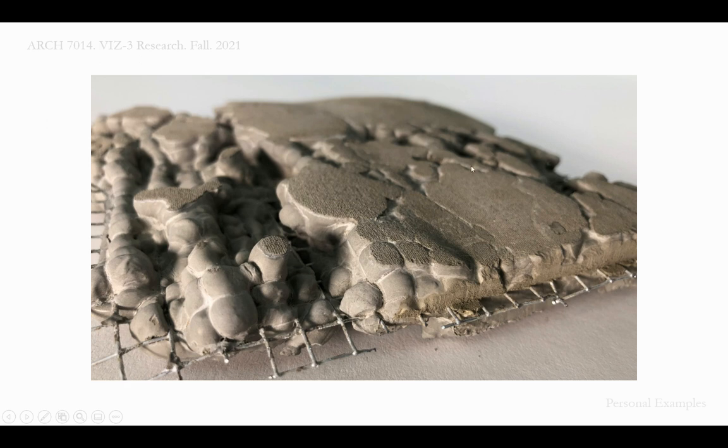Sometimes it got so close, because this was a pretend floor slab, so this mesh is kind of acting like rebar. The extruder got so close to what would be mesh rebar that it actually forced a lot of material through it and created these cool little pillow-looking things, clouds I like to call them, of concrete that poked through the mesh.